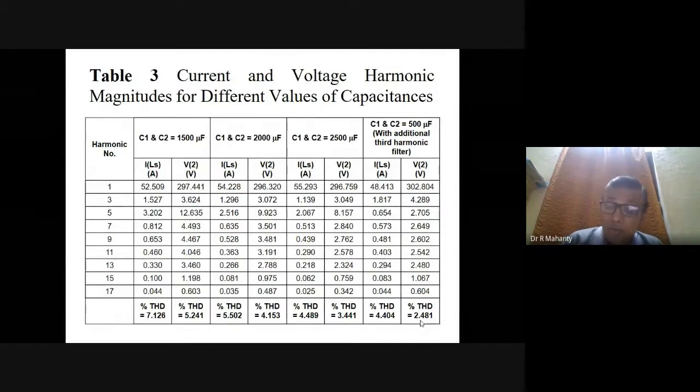Okay, so this is one of the things that I wanted to tell you: if we use a very large value of AC capacitor in the shunt passive filter, all the harmonic frequency current can be filtered out with one set of shunt passive filter tuned at the dominant harmonic frequency, and this filter has been named as quasi-passive filter. Okay, now let us see whether this circuit can be used for reactive power compensation also,